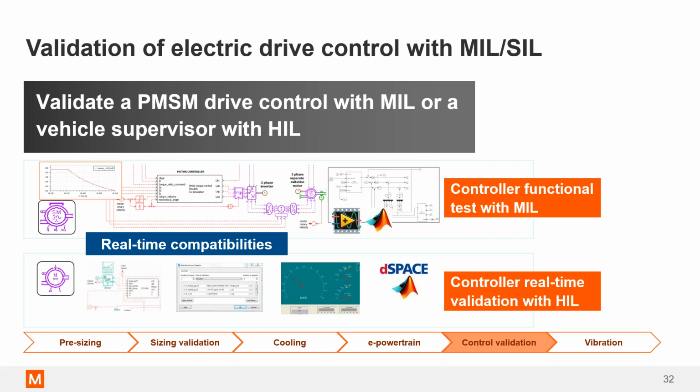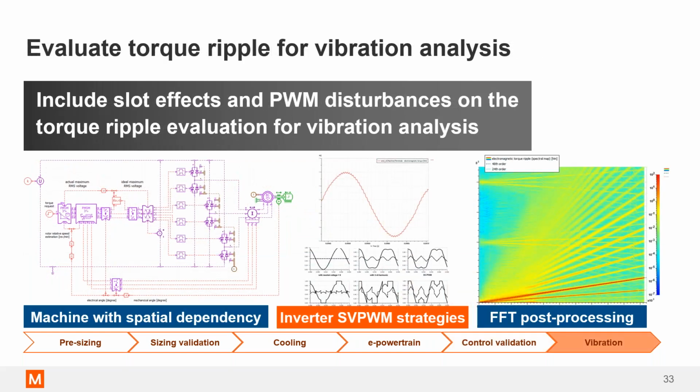And the last little bit that we want to mention is we talked about vibroacoustics, and we can do some interesting vibroacoustics at the system level. Just knowing from our motor design, we can look at how things such as different inverters or different control methodologies can change the input parameters into your motor, and we can look at how that might affect how the motor behaves.